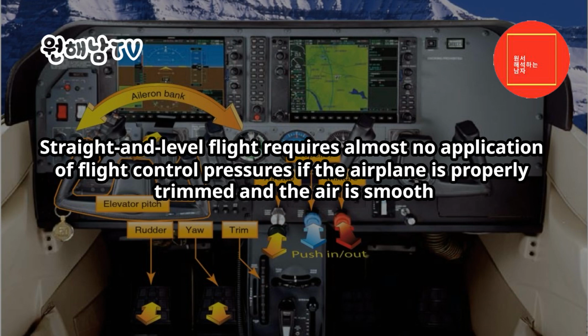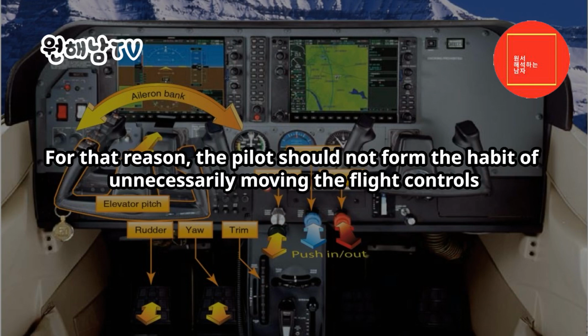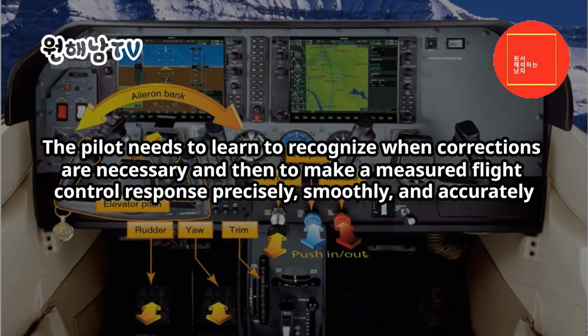Straight and level flight requires almost no application of flight control pressures, if the airplane is properly trimmed and the air is smooth. For that reason, the pilot should not form the habit of unnecessarily moving the flight controls. The pilot needs to learn to recognize when corrections are necessary, and then to make a measured flight control response precisely, smoothly, and accurately.